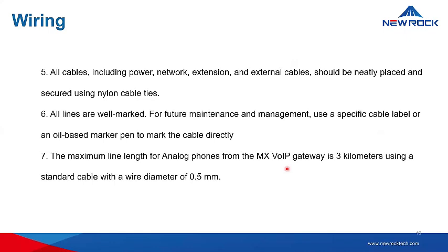Then make sure that the maximum line length for an analog phone from analog to the MX gateway is 3 kilometers using a standard. So do not go beyond that. The 3 kilometers is based on a standard wire diameter of 0.5 mm.